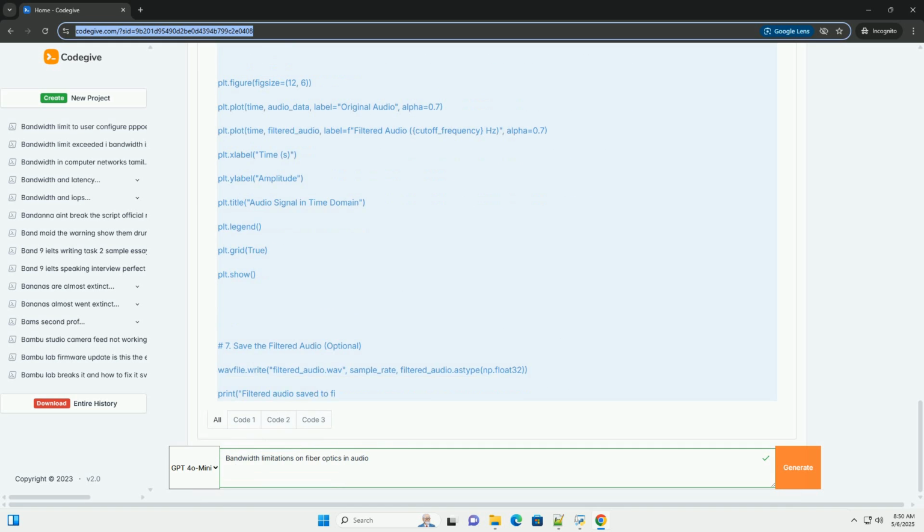2. Bandwidth concepts. Bandwidth, in the context of audio, refers to the range of frequencies a system can accurately reproduce. It's typically measured in hertz, kilohertz, or megahertz. Analog audio: the bandwidth is the range of frequencies the analog audio signal occupies. For high-fidelity audio, a bandwidth of at least 20 Hz to 20 kHz is desired to cover the full range of human hearing. Higher bandwidth may be required for ultrasonic information sometimes present in recordings, for example DSD.